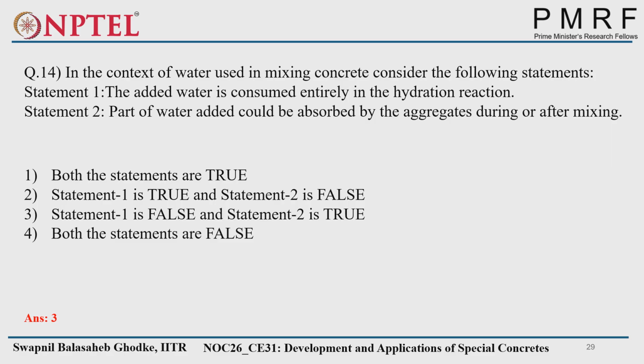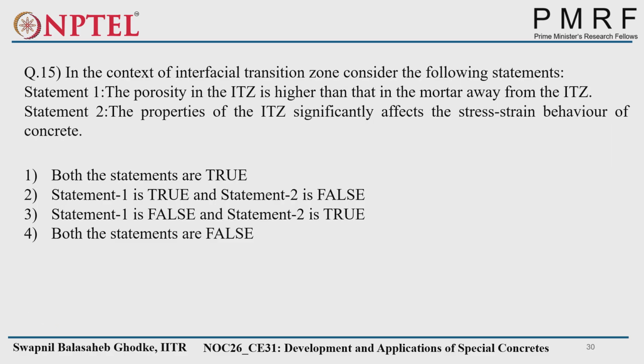And suppose you are using timber scaffolding, sometimes that timber scaffolding will also absorb some amount of water. So that's why statement one is false and two is true, because, as I said, aggregates will absorb some amount of water. That's why we use the aggregates in the saturated surface dry condition. So the answer is statement one is false and statement two is true.